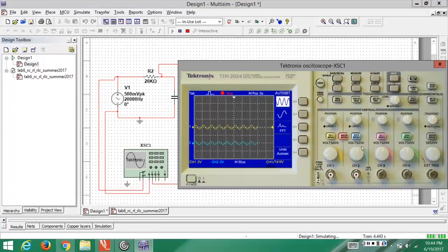And to do the same for channel 2, I look at the channel 2 panel and use the vertical positioning knob to bring it up and align with the x-axis as well. So now I have the x-axis as a reference for these waveforms. It will help me to analyze the signals better. I will change the volts per division to enlarge the waveform to get a perfect reading.